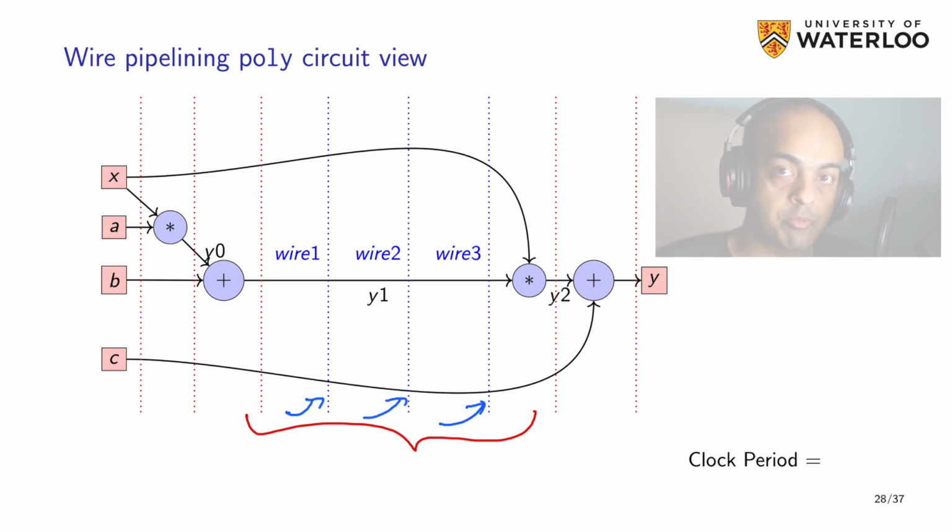Right, so you need to add these pipeline stages sort of geometrically distributed at equal lengths between the source and the destination. And what this does is it takes the wire and breaks it up into lots of these tiny chunks, right? And we will revisit how wire delay grows as a function of length later. But the clue that I'm going to give you is doubling the length of the wire makes wire delay grow faster than 2x.